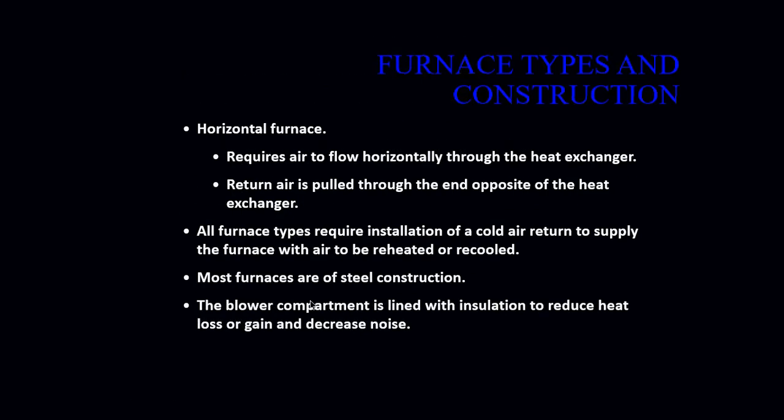Okay, horizontal furnaces also require air to flow horizontally through your heat exchanger. The return air is pulled through the end opposite of the heat exchanger, and all furnace types require installation of a cold air return to supply the furnace with air to be reheated.